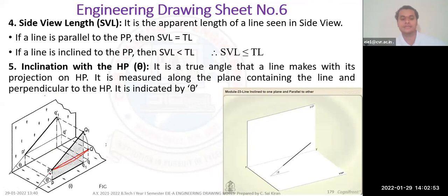Now I am taking an angle theta, extending at 30 degrees. Then I take a compass and draw the arc. Wherever this arc touches, I draw the vertical line, because this is my top view. This is P and Q1. In the top view, I need to project as small letters, and in the front view, I project as small letters with a dash.